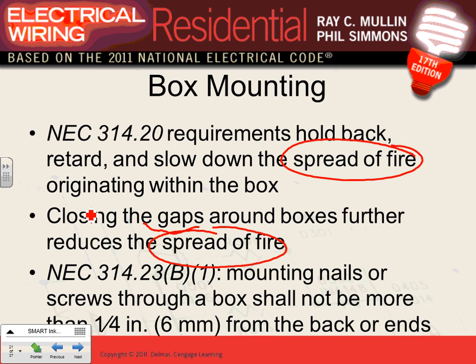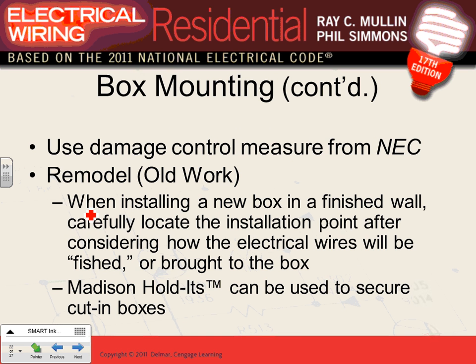There's a couple of requirements, guys. You have to maintain 1/4 of an inch. We'll talk about this one as we go. When you put your boxes, you have to maintain 1/4 of an inch when you drill, from the place where your nails are going to be located, so you don't bust right through the cables.